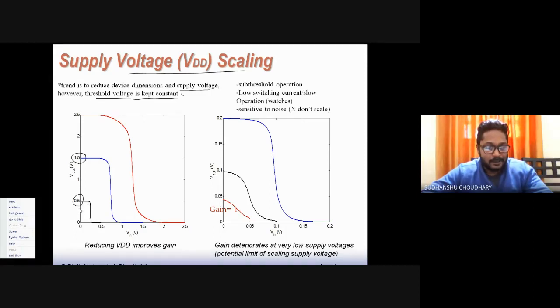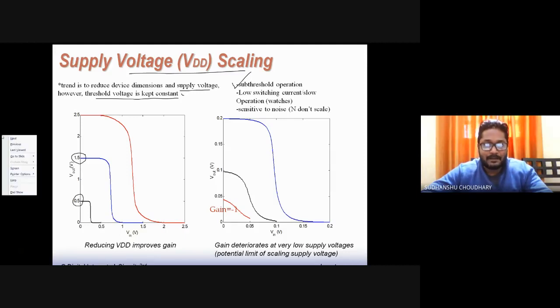I mean, at VDD of 0.5, which is very near to switching threshold, how can the circuit work, or CMOS inverter characteristics are still maintained, right? So how is it possible? So the answer lies in the sub-threshold region of operation of the MOSFET. We discussed some time back that even if VGS is applied, and if VGS is less than threshold voltage also, still the MOSFET conducts. Okay?